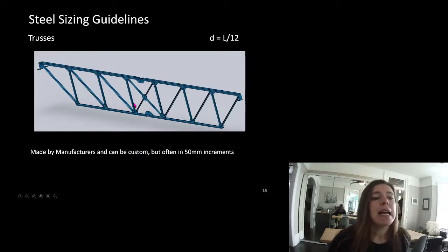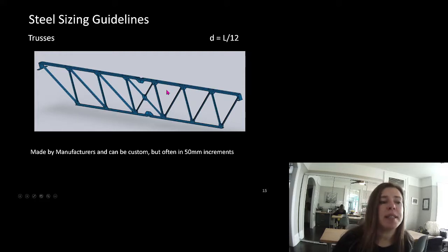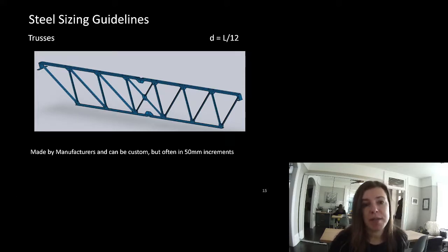Okay, a steel truss. It looks a lot like an open web steel joist. It is not an open web steel joist. But an open web steel joist is a truss. It is a type of truss. It is just a manufactured, standardized truss that does light work. It doesn't do heavy-duty work. A truss is something above and beyond. We would often use a truss instead of a girder. So if we see a job that's pretty heavy-duty, we might say that should be designed as a girder, or maybe we'd make a custom truss.